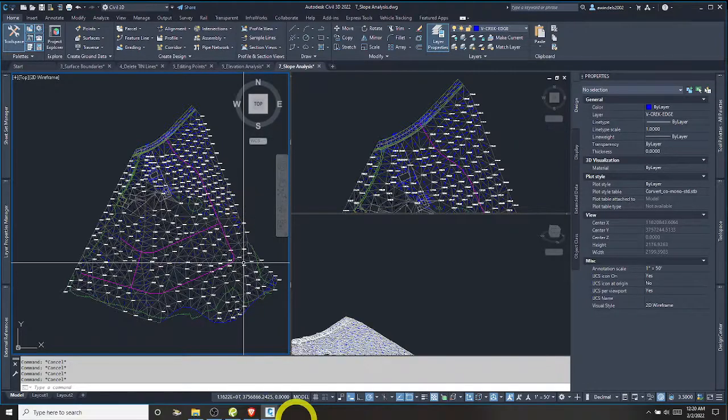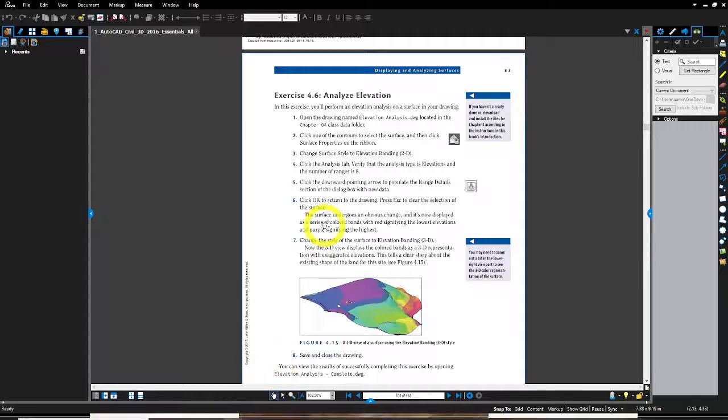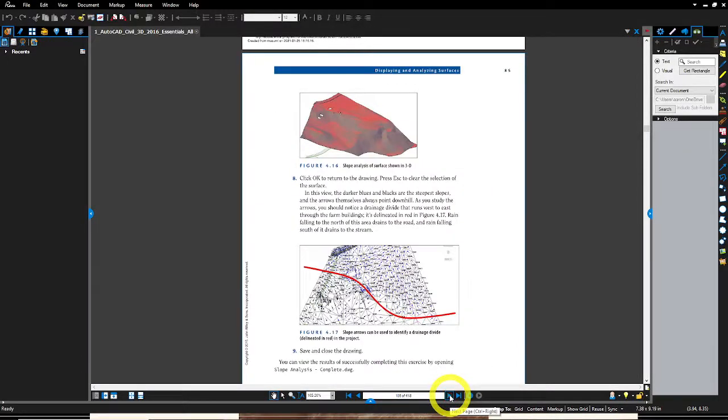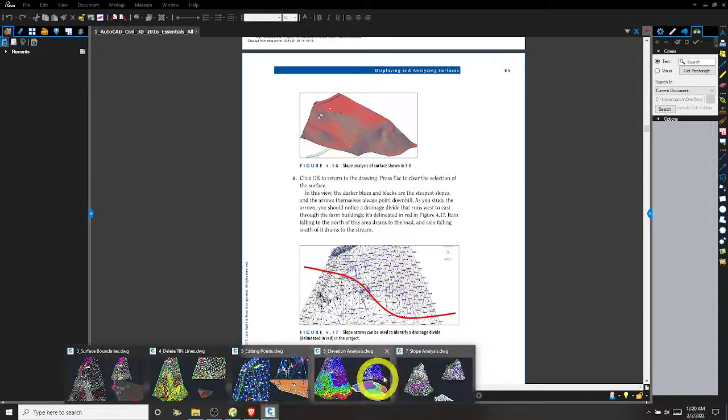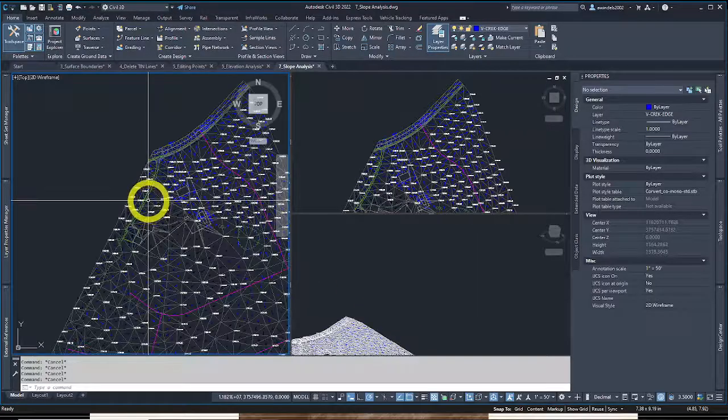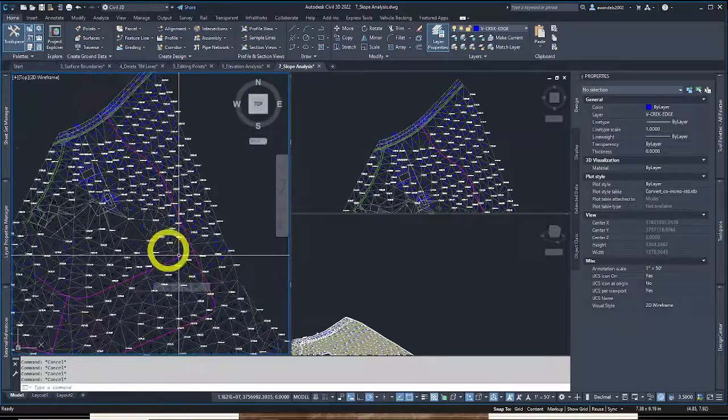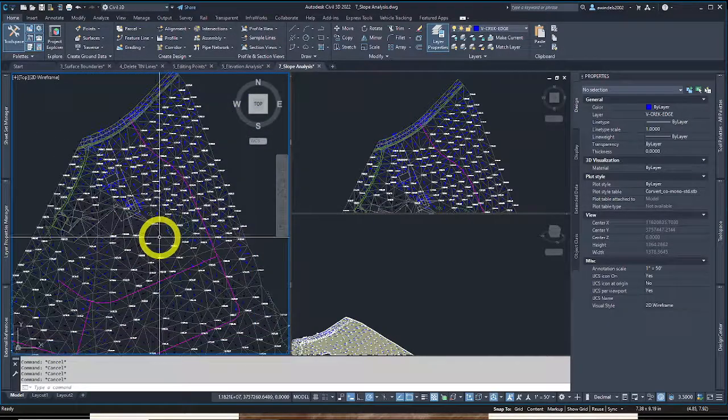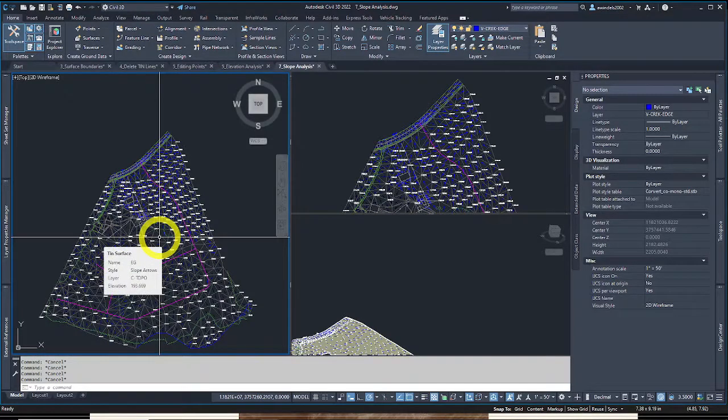The picture on page 85 is a really good example of how a more senior engineer, or someone not necessarily a senior level engineer, might see a real drainage divide really quickly, a delineation. You can see where it's almost kind of a ridge on a local site. This helps you see that a lot quicker and more surgical, really. You can kind of see this all tends to want to slope to the south, and this wants to go to the north quickly. This is a good way to analyze a surface for a more skilled engineer, possibly, or someone a little newer that needs a little bit of a refresher on how to better analyze surfaces.